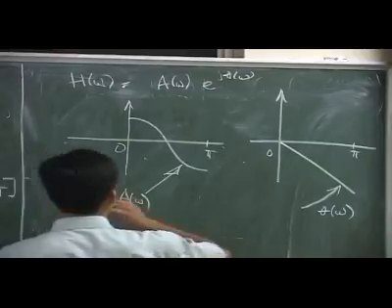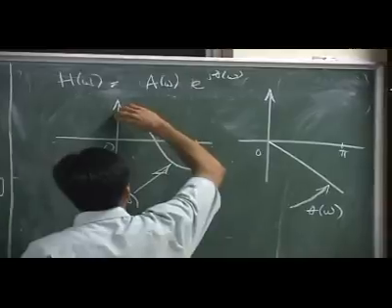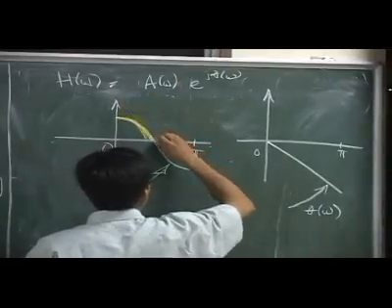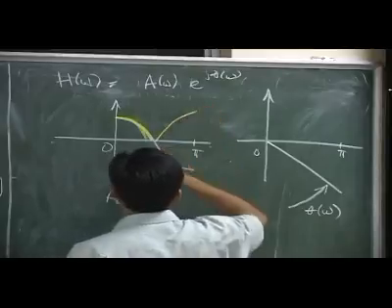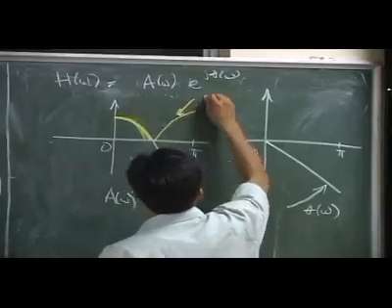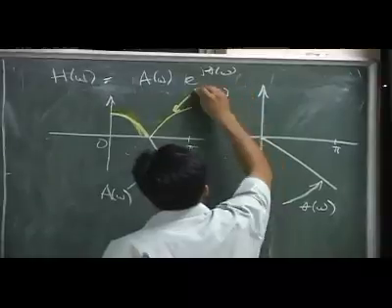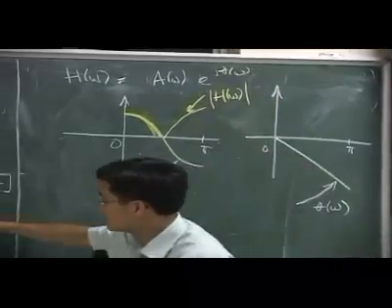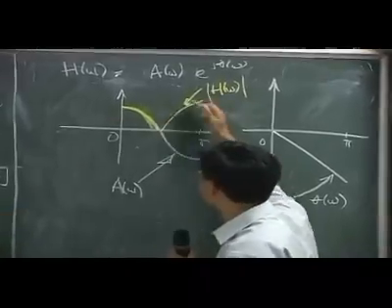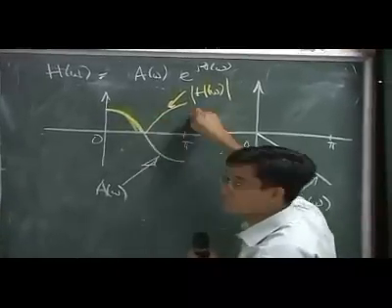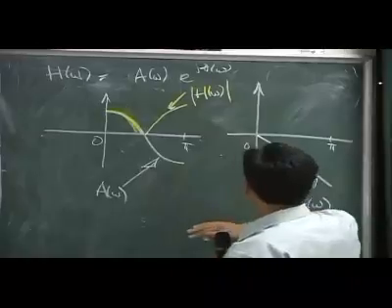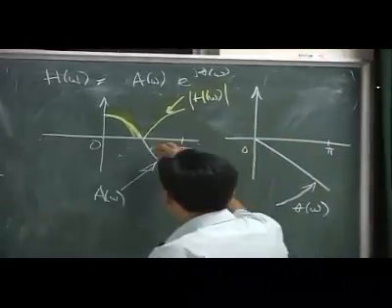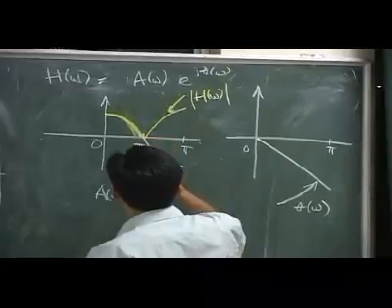Now when I have to convert this to the complex form, to find out the magnitude and the phase, the magnitude of this would be this function, and then I take the absolute value of it, which would be this. So this would be the H of omega magnitude, right? In the range where this is positive, I just take it, but where it's negative, I have to take the negative part. And the phase of this, let's call this thing here pi over 2.